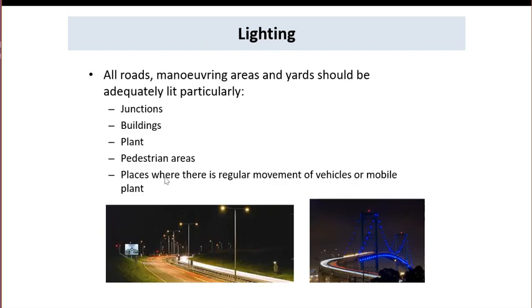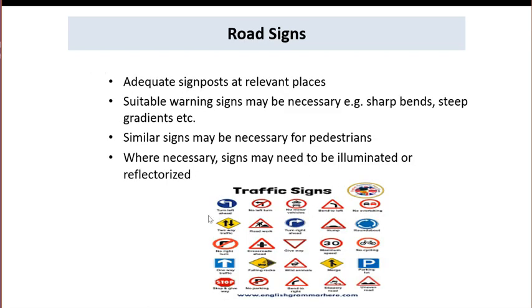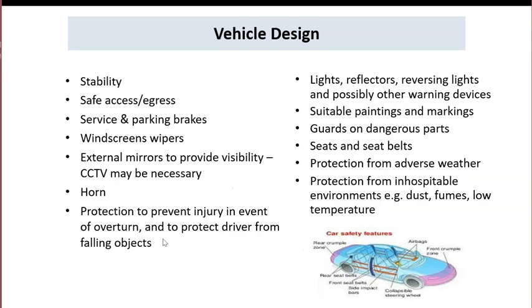And the lighting must be well lit, especially near the junction and the pedestrian area, and the road signs must be clearly placed at the relevant places. Especially put a warning sign at the sharp bends and steep gradient, and illuminate it or reflectorize the sign.